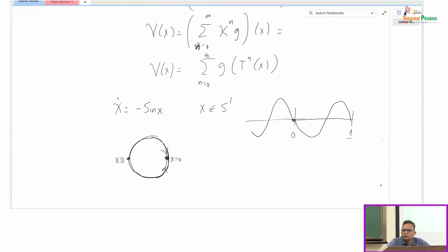It's not, right? Why? Because there is an x equal to pi. So if you start at x equal to pi, you will never get to x equal to 0, right? Except for x equal to pi, no matter where you start, you'll get to x equal to 0. So x equal to 0 is stable in an almost everywhere sense. That is, everything gets to x equal to 0 except for one single point, which is a measure 0 set. So this is an example of a simple system where you have an equilibrium point which is not globally stable but almost everywhere stable.